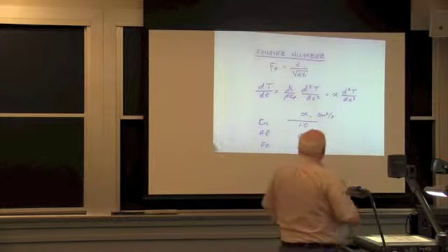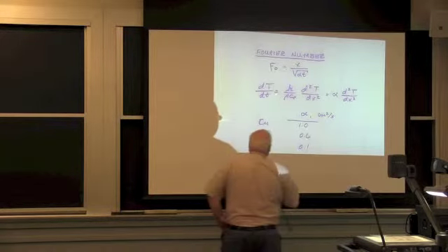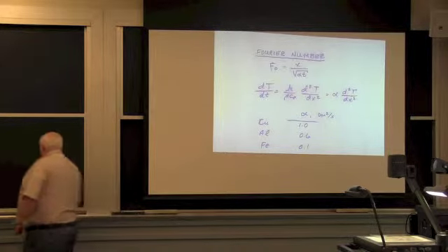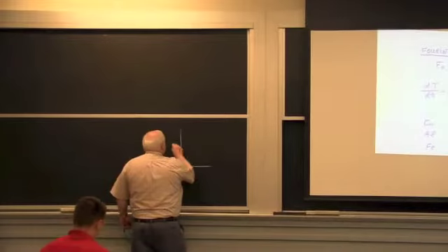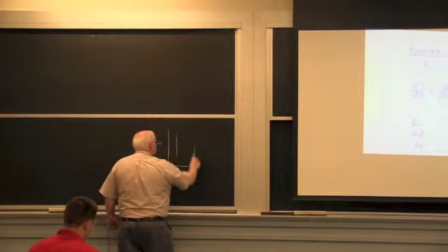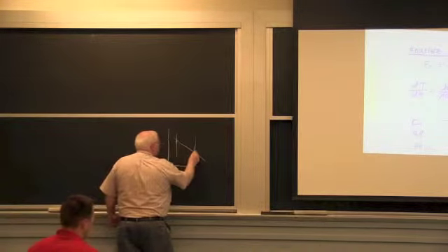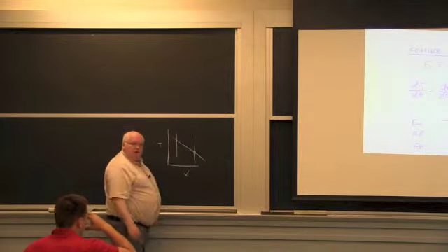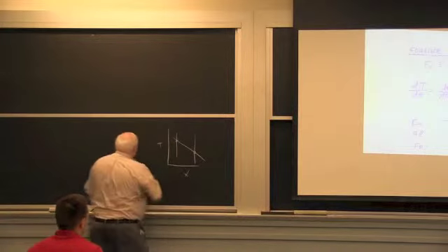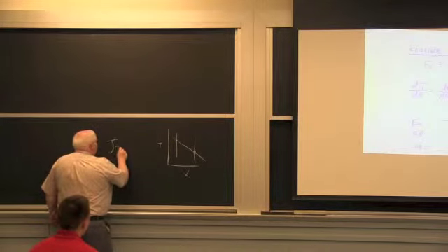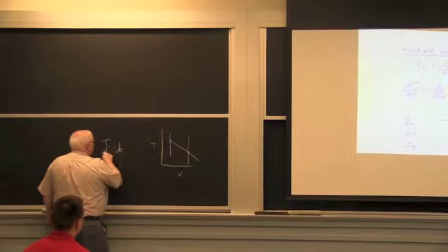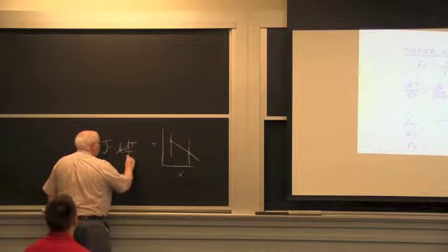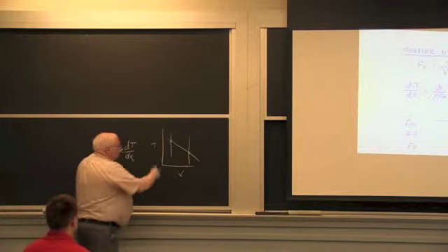Now, the Fourier number for heat transfer, Fourier's second law, which comes out of the first law. The first law basically just says if I've got temperature and distance, the heat flows down the temperature gradient and you get a steady state. And if it's Cartesian coordinates, it should be a straight line as long as the thermal conductivity doesn't change, and Fourier's first law is J, the heat flux, is minus K dT/dx if we're talking about things in one dimension. Okay? Just a straight line.